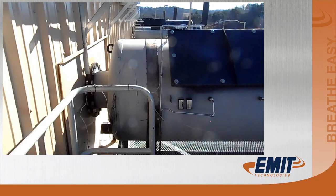Okay. I always want to look for the obvious on catalyst failures or when things aren't going right. The obvious on this picture is the white tells you that this has been very hot. We use a high temperature coating on the catalyst housings. You can see the door did not change color, but the housing itself changed color. And look down the line, you can see this one and you can see this one were also white.